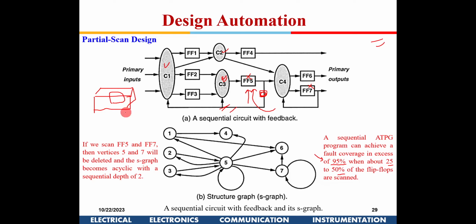So on the ground itself, when I'm powering on the system every day, every sortie, I would want the system to do a built-in test and tell me the system is okay, right? I may not be functionally using it on the ground. So there is a requirement that any VLSI chip or PCB board, when I'm powering on, should run a built-in test and tell me, if this is fine, you could use it.